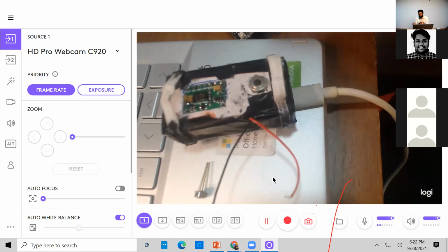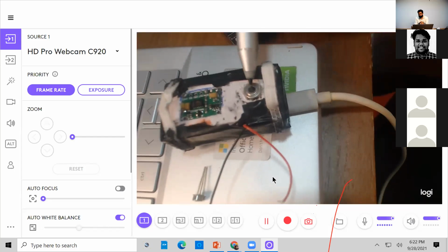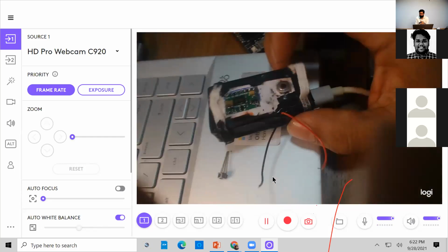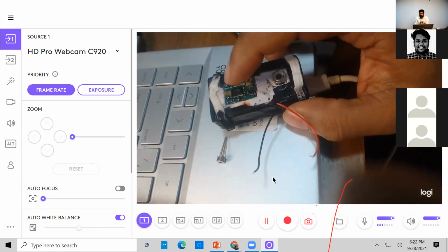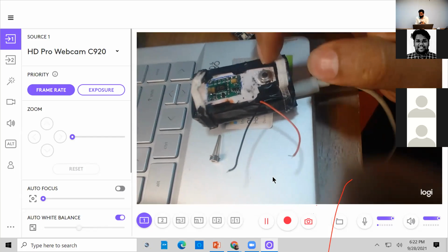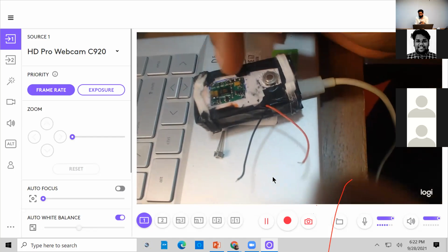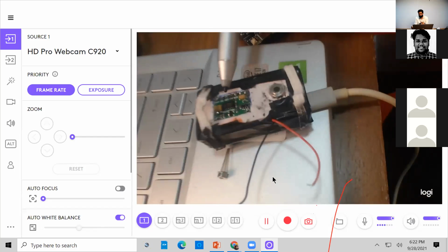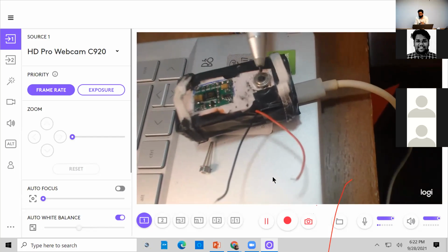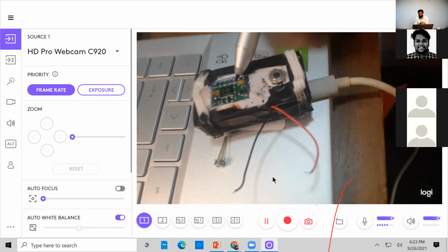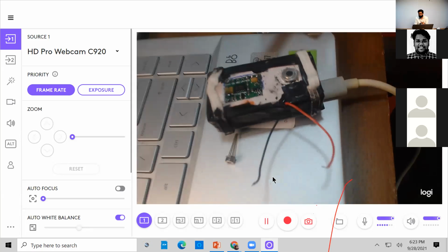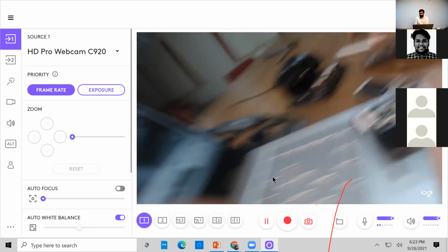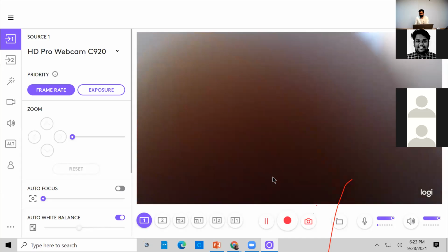If you have a maximum of 3 to 4 centimeters of distance between the sensor and the human body, it will give you an accurate measurement. I will show you how to measure my body temperature, heartbeat and SpO2 levels using these sensors. I am using different sensors, the MLX 90614 for temperature and the MAX 30102 for heartbeat and SpO2, so that you can understand multiple sensors for your application. Normally, this sensor is not required for measuring body parameters, because the MAX 30102 also provides body temperature, SpO2 level, and heartbeat. I'm just trying to clear that up and show you the differences.